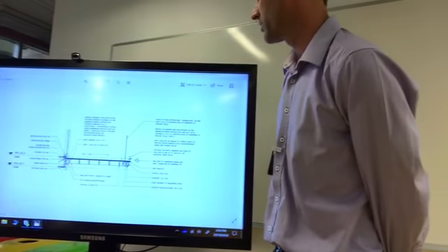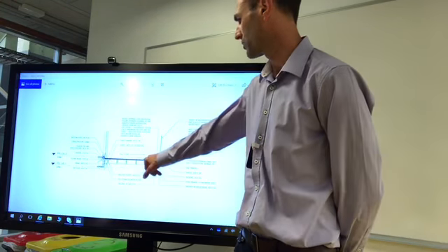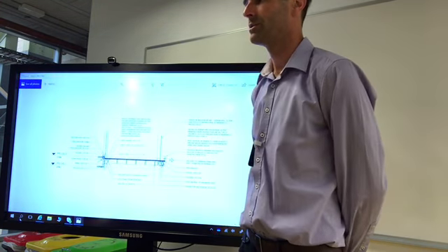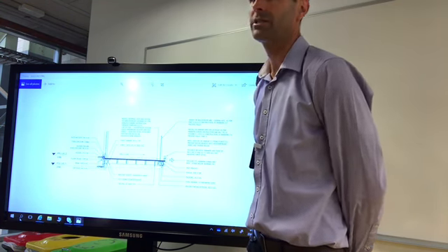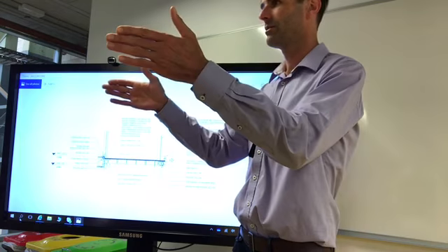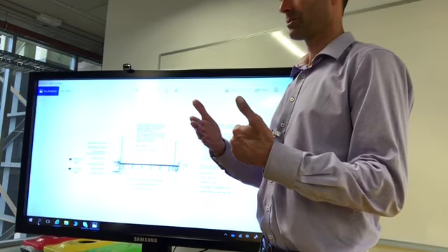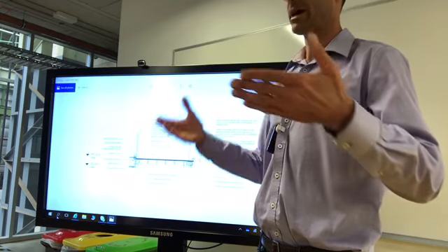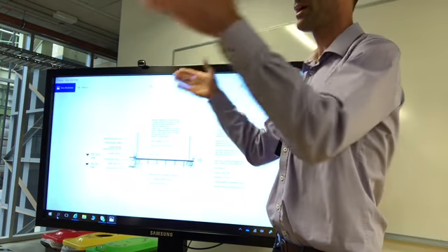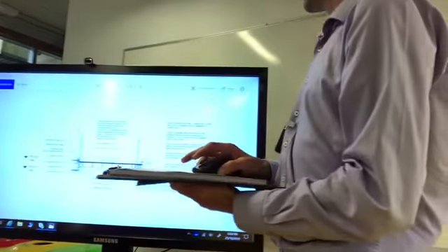Although if you were going to be framing it up, this detail relies on joists running parallel to the edge of your building, which means you'll need to have supports carried out at set distances running perpendicular to your building as well. So that detail would then also have I-beams in the background that your joists are locating on, and they cantilever out from the building to carry those loads. So that's that one.